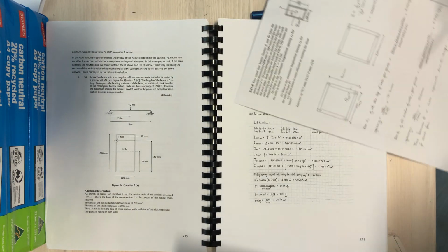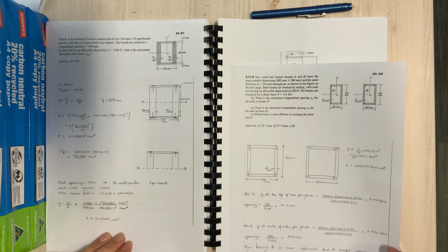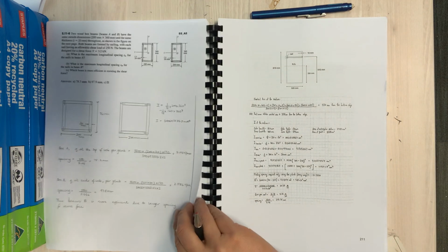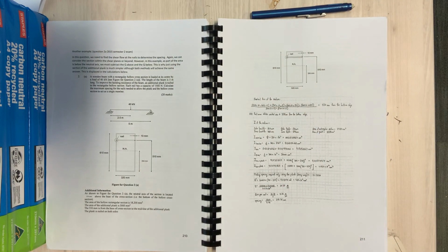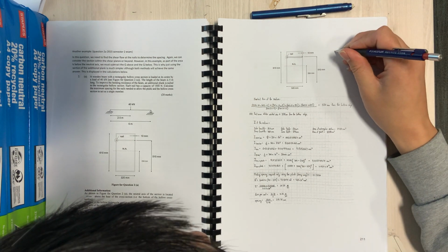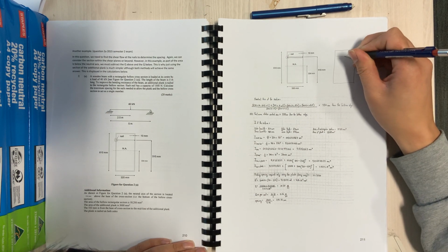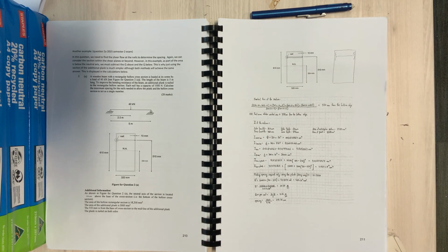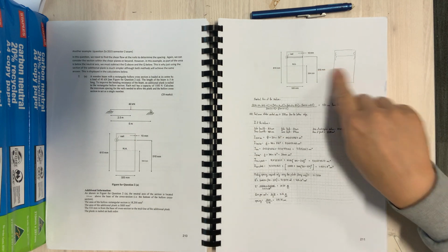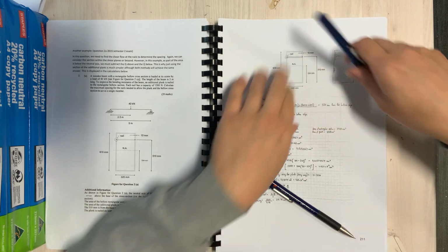Firstly, the related solutions are here for the nail spacing, and also here, so they're in the course book already. So with this one here, what do we do? We've got our box beam, I'll just draw it like that, and then we've got this bit which has been added, and then you've put a nail through it there, and then there's 2 shearing planes. So how do we do the calculation? We do it exactly the same as before.